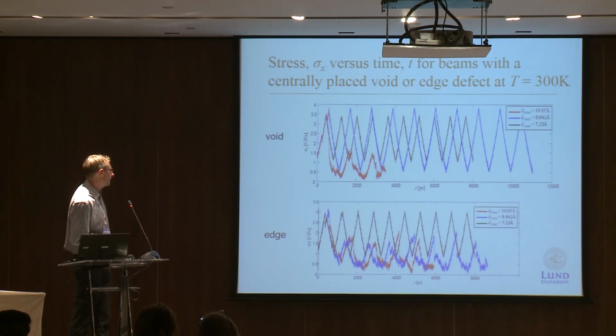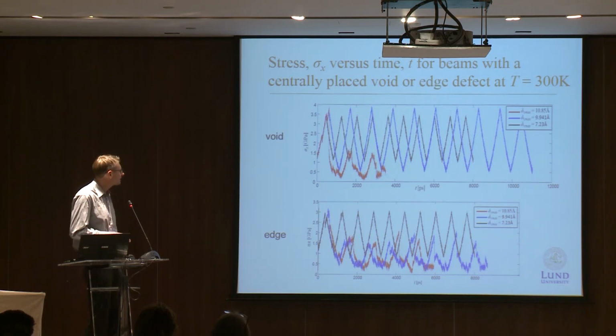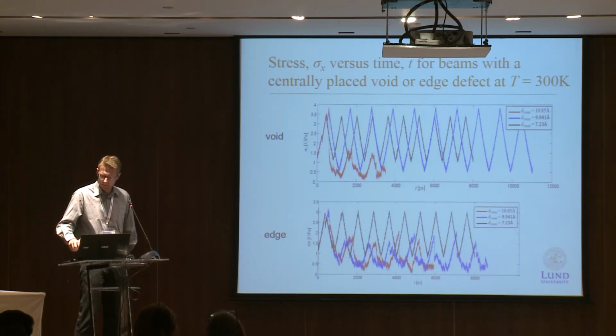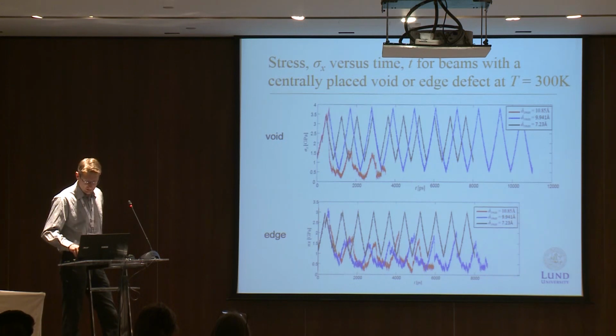The intermediate value here, we see that the stresses go down. We have some kind of healing also in this case. But it can withstand 8 load cycles. And then for the lowest, we reach a steady state immediately. I would expect infinite life.